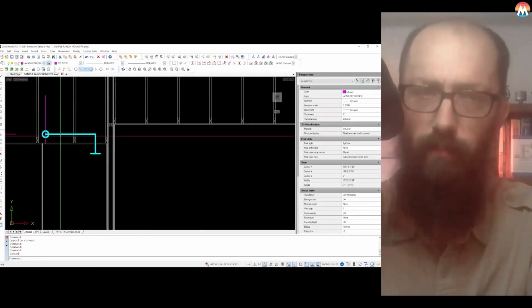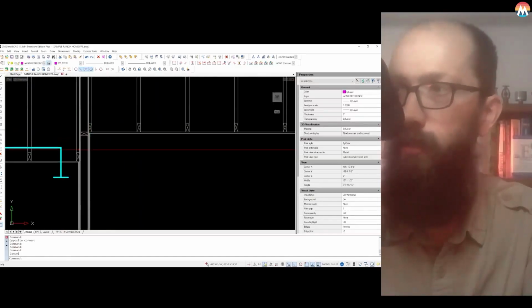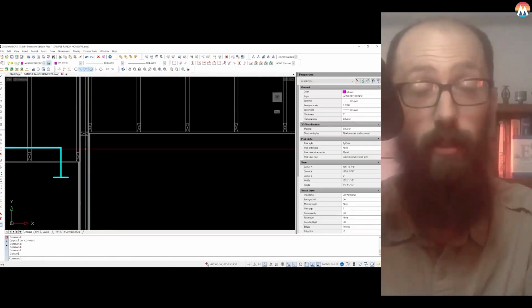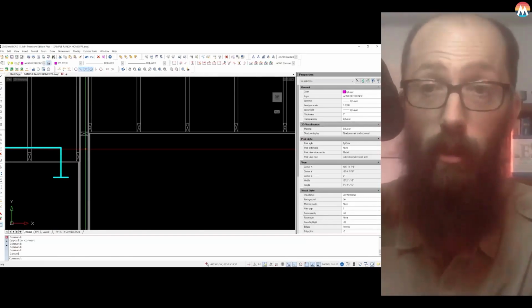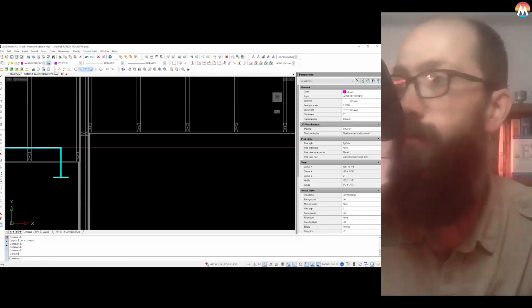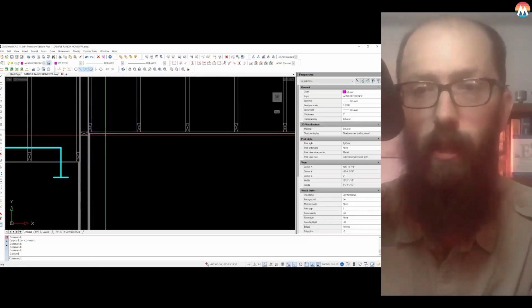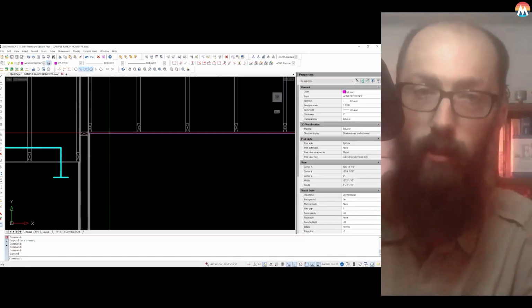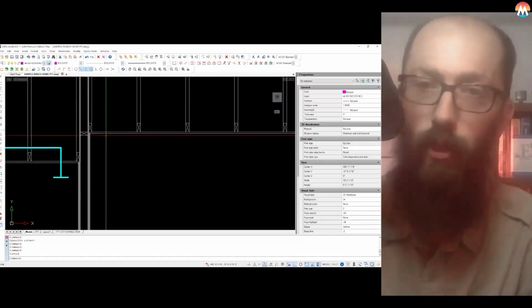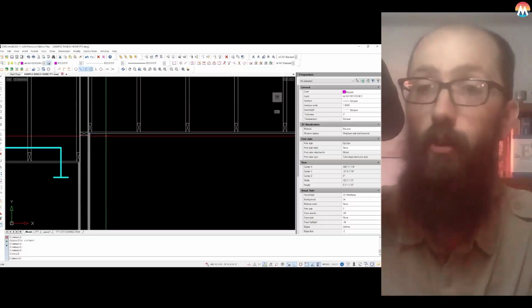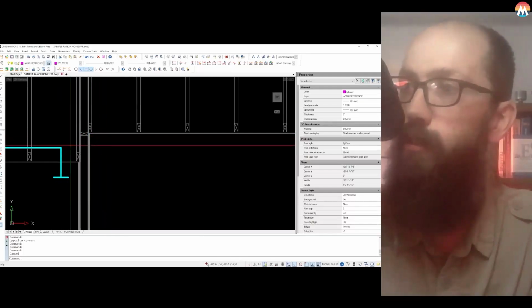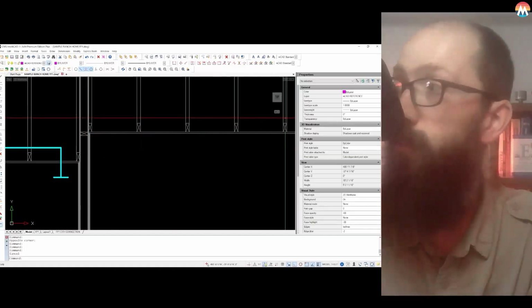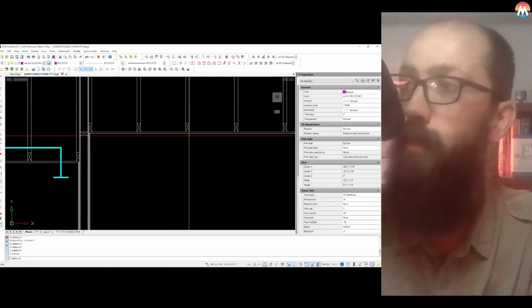Now, one thing that's interesting that we haven't dealt with yet, this is why cross sections are important to use if we have them, because you notice things that you don't notice as easily on plan view. There is a change in ceiling elevation right here. And I noticed it, but I just ignored it until we got to this point in the course on purpose so that we could address it now. So we are going to need to rise up and continue across this direction at this higher elevation.